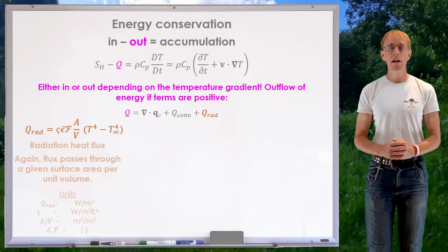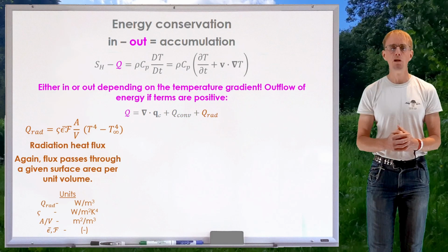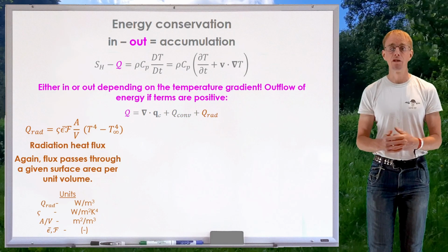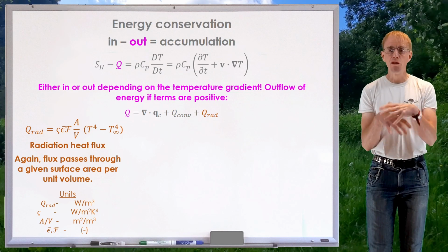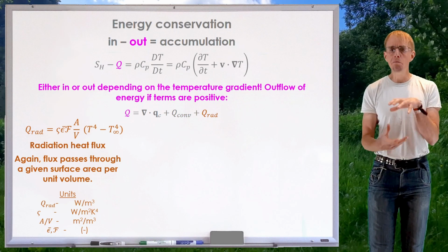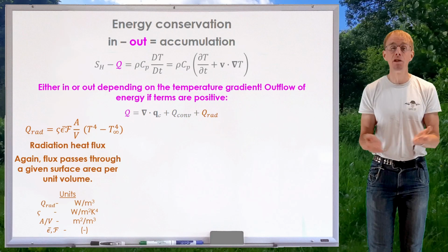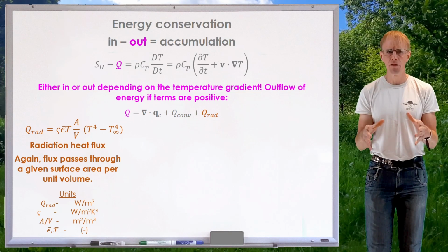What we see is that radiation heat transfer, as measured in watts per meter cubed, consists of the Stefan-Boltzmann constant, little sigma, the effective emissivity of the surface and the heat source, and then how much of the radiation, let's say, emitted by the heat source is gathered by the surface. That's captured in script F, my view factor. More about this later on.